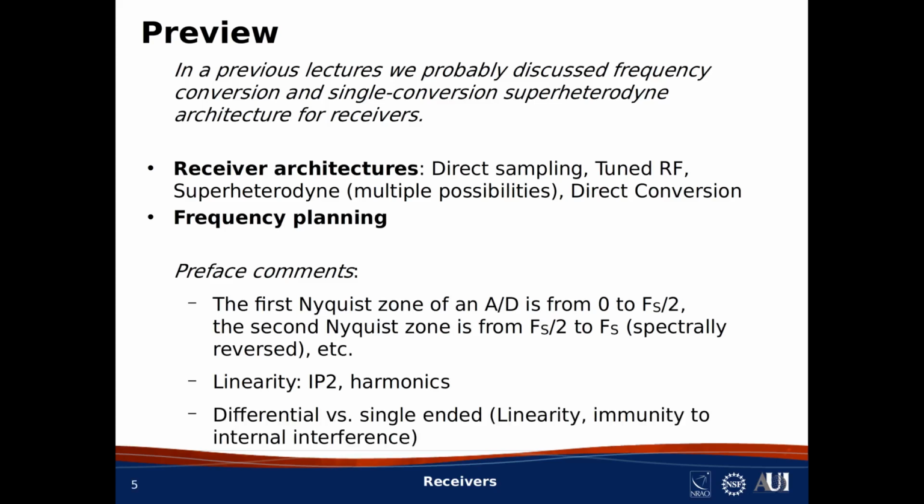The third thing that will come up is the distinction between differential and single-ended signals. Now, this topic is completely in the weeds unless you fancy yourself an electronics engineer, but it's useful to know that differential signals enjoy some advantages in receiver design, and these include improved linearity and improved immunity to internal interference.